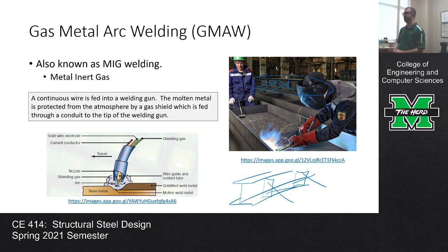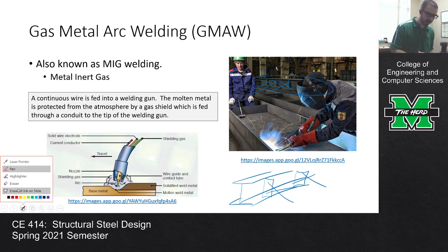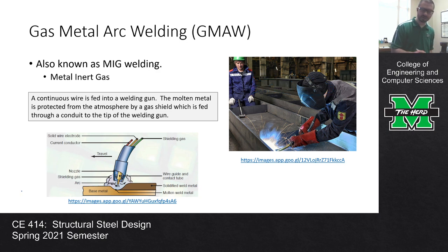We spend a lot of time talking about bracing and Lb and all sorts of that stuff, so we will sort of indirectly cover that later in the semester as well. And if I have time, I'll talk about shear resistance. One of the things about steel design, particularly steel in buildings, is that shear on beams tends to not be a big deal. It can be for plate girders and bridges, but for beams in buildings it tends to not be the biggest concern in the world, and that'll be more clear as we progress throughout the semester. All right, any other questions?